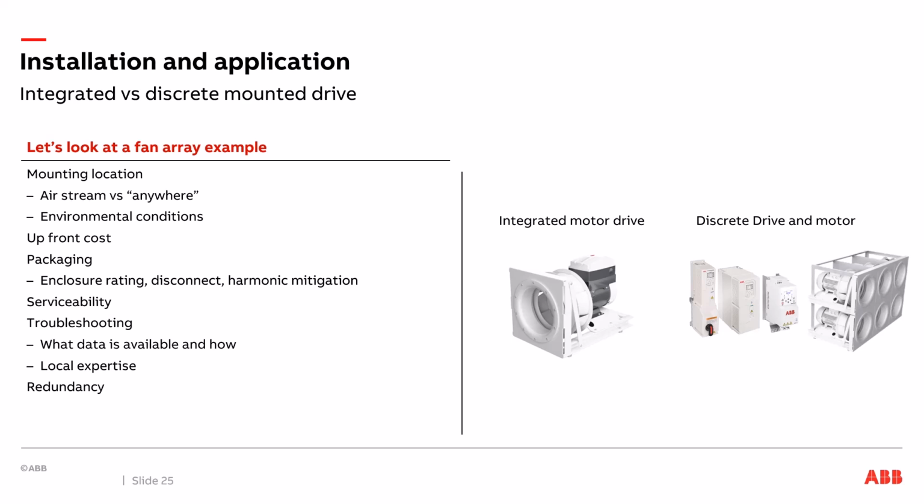So whatever my fan array air temperature is what I'm being exposed to. If I'm a nice solid 55-degree discharge air temperature and that's all that unit ever does, that's not a bad environment for that drive. If I'm in a situation where it might be a staging solution, it might go from nice 55-degree cool air to somebody opening up a service door and now I've got 105-degree air that's horribly humid and everything condensing in there. Yeah, it's not a good situation. So you've got to kind of consider that environment.